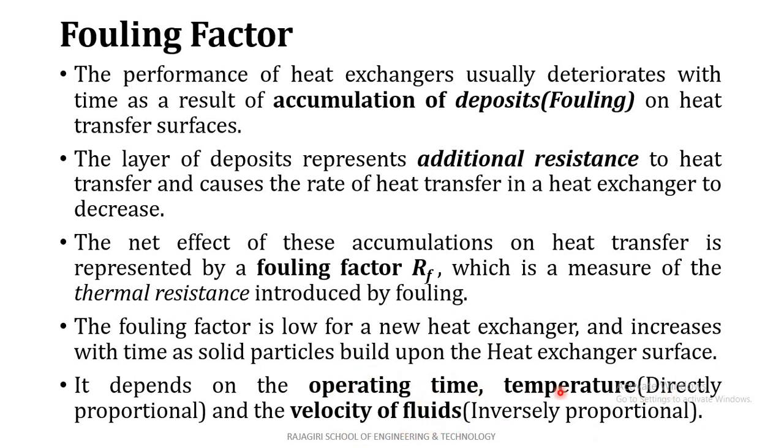The first two, operating time and temperature, are directly proportional to the fouling factor. If the operating time increases, the fouling factor increases, and if the temperature of the fluids is at a higher level, then the fouling factor will be higher.